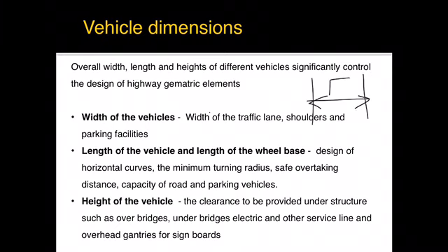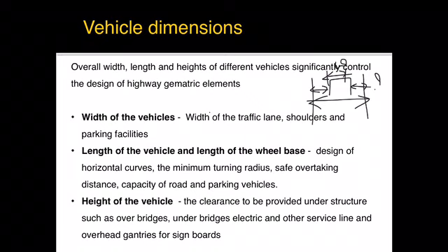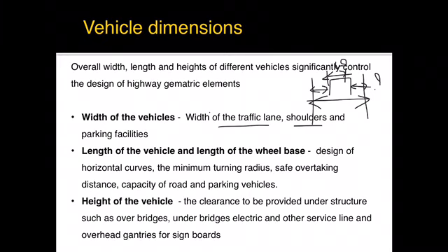So now here, the width of the vehicles that you design for should be such that you have side clearance and the maximum capacity of the road is achieved. Whenever you decide how many lanes you have to provide and what the shoulder widths should be, all these things will be based upon the width of the vehicle.